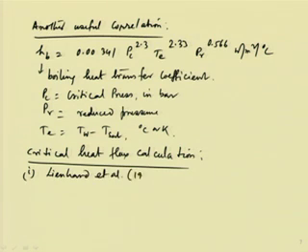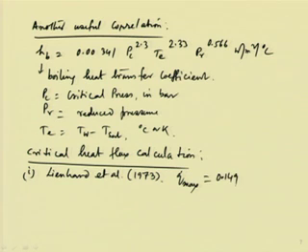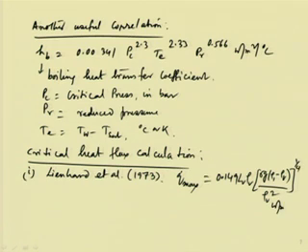And in 1973, here the Q dot max. So, critical heat flux, which is nothing but the maximum heat flux also we are telling, because if we go beyond that, then if we do not have the control, it may switch over to the burnout conditions. So, Q dot max is equal to 0.149 into LV into rho V, okay, and then we have sigma, then G into rho L minus rho V, by rho V square whole to the power 1 by 4,